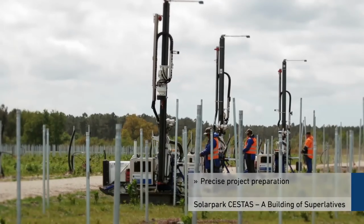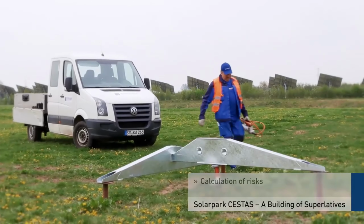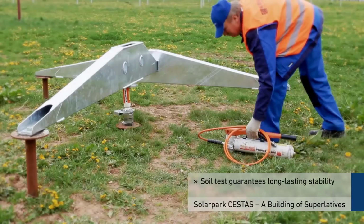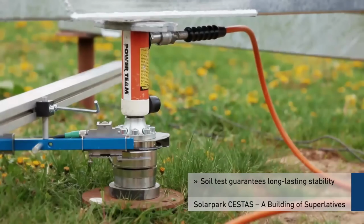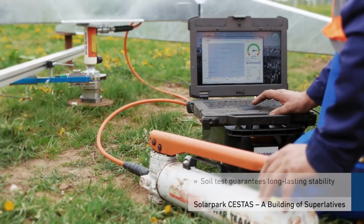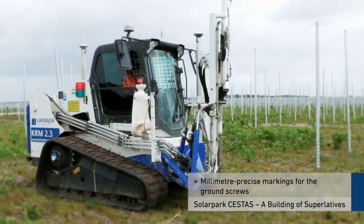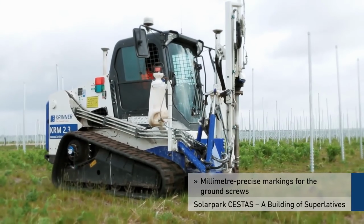With help from special machinery developed by Krinner, time-consuming and cost-intensive risks can be calculated in advance. In the first step, the soil conditions are inspected to guarantee long-lasting stability and fastening of the foundations. In the second step, a GPS-controlled measuring robot creates a detailed site plan on which the markings for the ground screws are placed with millimeter precision.